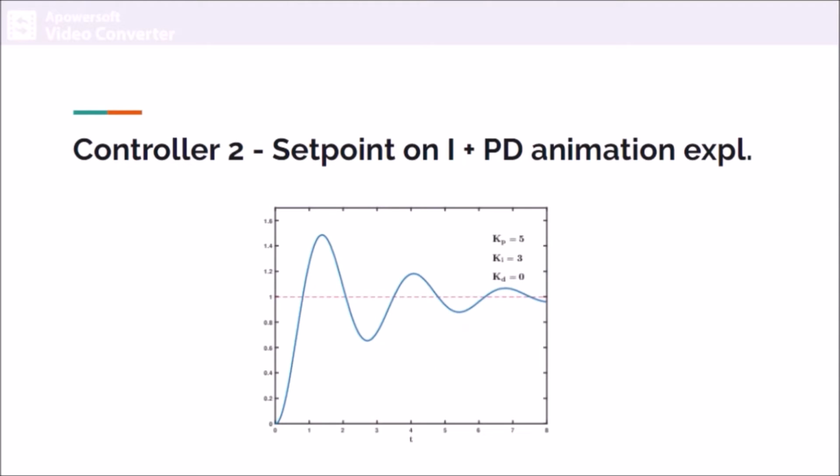The next slide is a very good slide that explains the PID controller in an animated way. It gives you the intuition of the proportional gain, the integral constant, and the derivative constant. As you can see, the more gain you add, the more oscillation, and the more integral constant, the more you can offset the entire system up to the set point, and the derivative term will anticipate the change and remove any oscillation of the system, as you can see.